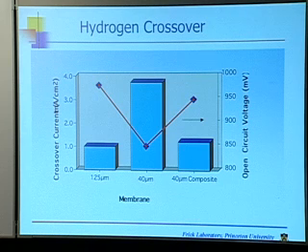Turns out there's another positive effect. You don't see this effect when you're working with 125 micron thick membranes, but I think I mentioned to you, everybody wants to go to thinner membranes, and in fact, the state-of-the-art material today is a 40 micron thick membrane. One of the issues you have to deal with for your membrane material, including Nafion, is a so-called crossover problem, which I haven't really talked about very much, but it's very simple. Nafion is not a permanent barrier, not an ideal barrier for the gases staying on the appropriate sides of the cell.